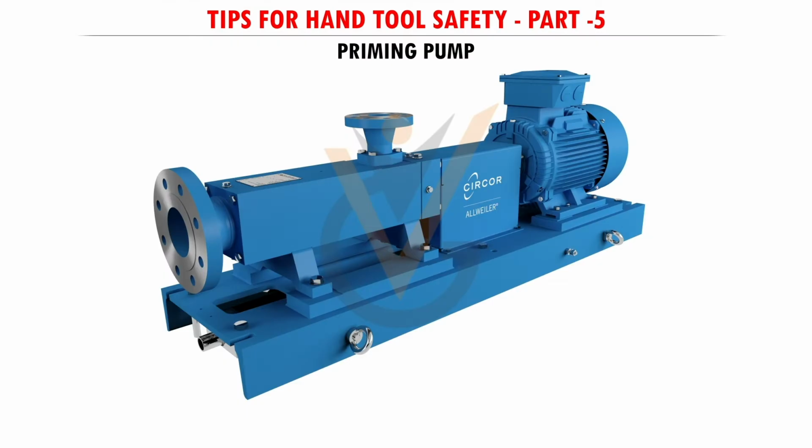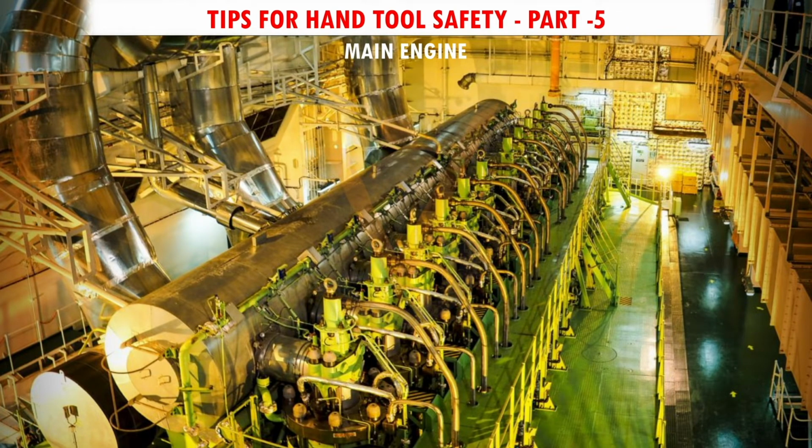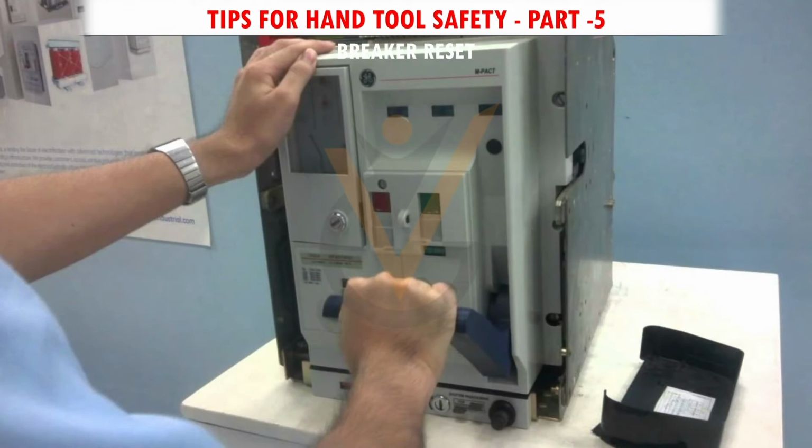Before starting the generator set, start the pre-lubrication priming pump if the supply for the same is given from the emergency generator. If not, then use a manual priming handle, provided in some generators. Start the generator and take it on load. Then immediately start the main engine lube oil pump and main engine jacket water pump. Reset breakers and start all the other required machinery and systems. Reset breakers that are included in the preferential tripping sequence.